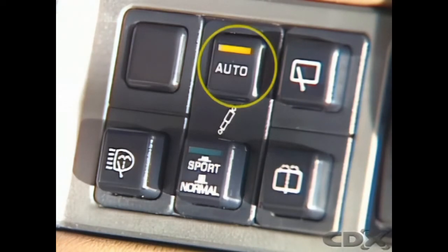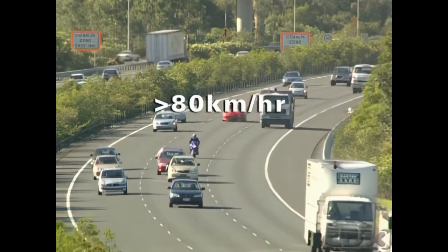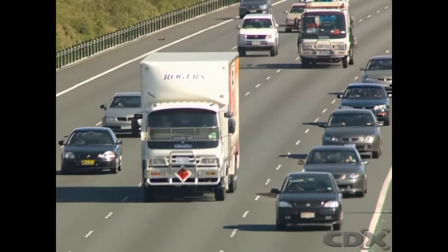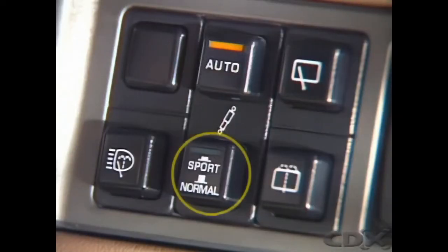In the auto position, the dampening effect at the front wheels is increased at road speeds above 80 km per hour. This improves vehicle stability at high speeds. The rear shock absorbers stay at their normal setting.